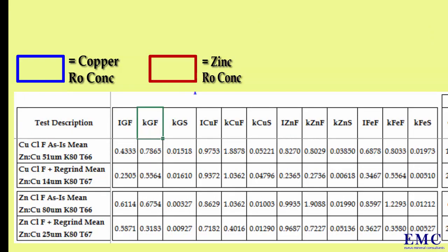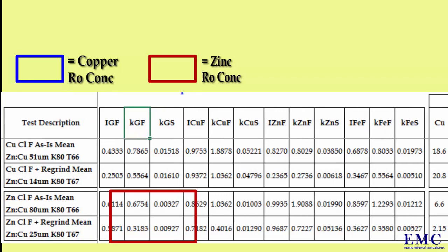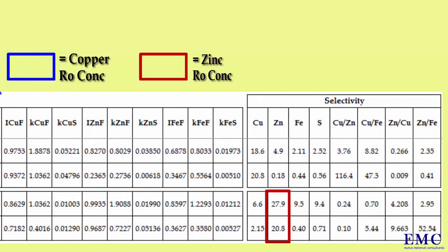In the zinc regrind, the aim is to liberate sphalerite from pyrite, and not so much to improve selectivity between sphalerite and gangue. And the kinetics show that this is being done. Gangue kinetics decrease a little, but do not change zinc selectivity relative to floatable gangue. The real improvement is seen in zinc-iron selectivity, which indicates that sphalerite is being liberated from pyrite.